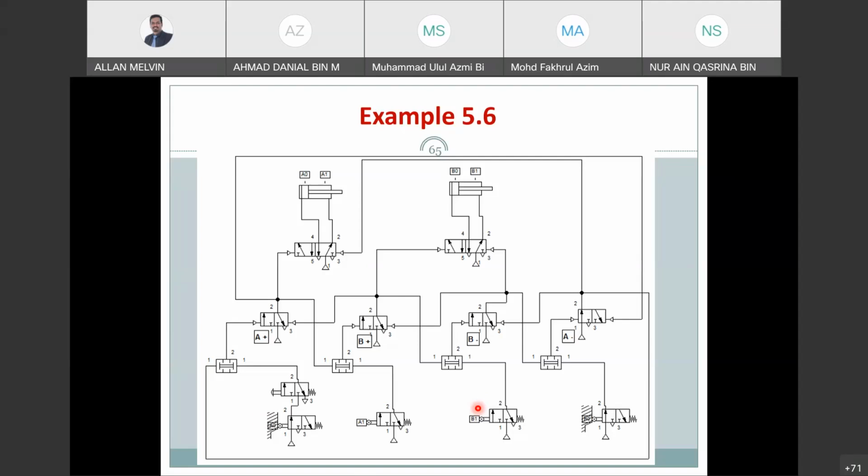It's more efficient. More organized. Okay, so it's actually organized like for me. I don't know, it can be argued. Tapi for me, step counter is more organized, sebab dia arrange based on sequence. Sebab kalau sequence you perlukan A plus, B plus, A minus, B minus, you just change dekat sini, the sequence. And pastikan the actuation is given correctly. Follow the sequence yang you nak lah.